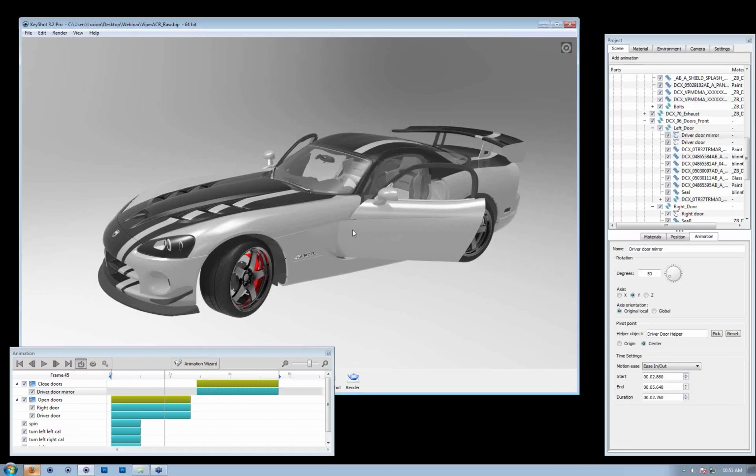This is what it does now, it tries to keep it very simple. It uses the center point of your cylinder as the center point of the rotation, but it actually retains the axes of the part that's being animated. So if you're setting your rotation animation to local mode, if that part has tilted axes, it'll retain that. But the cylinder won't. This is something we'll need to expand on in the future. You can tilt the cylinder all day, and all it's going to provide to the animation is a center point.